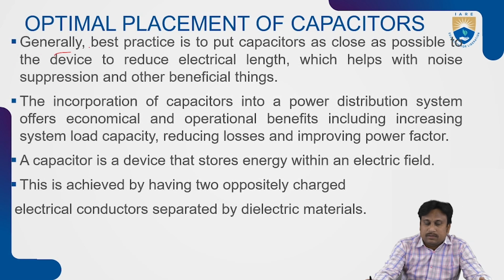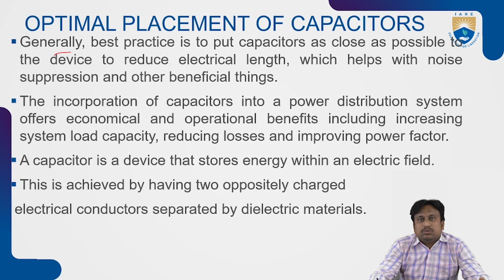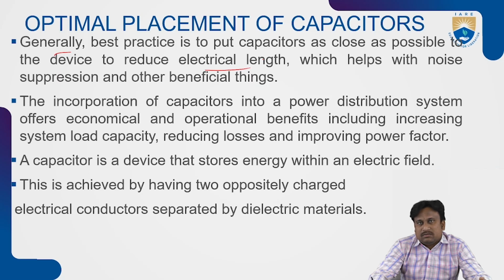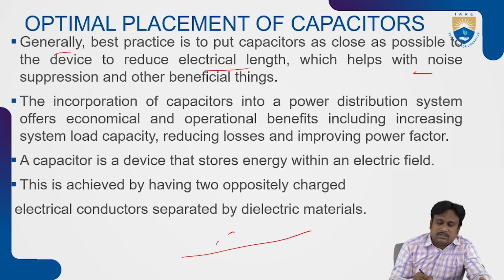Generally, the best practice is to keep the capacitors as close as possible to the devices to reduce the length of the electrical line. When you insert the capacitors nearer to the device, it reduces the electrical length, which helps with noise suppression. Whenever the line is energized, the expectancy of noise is more around the boundaries or region of the line.